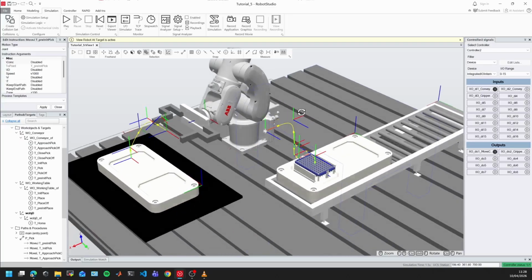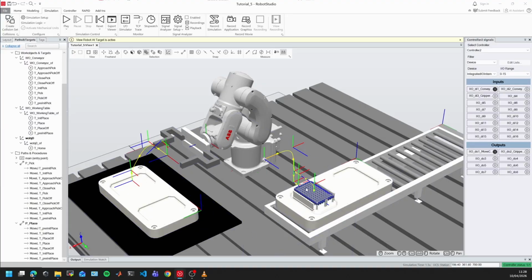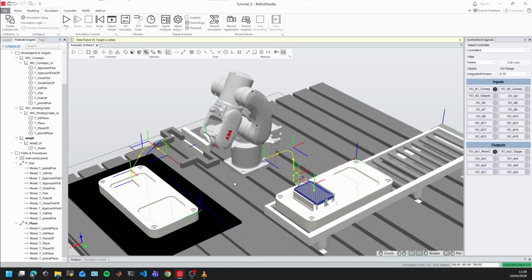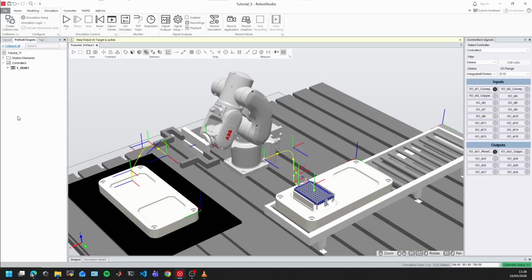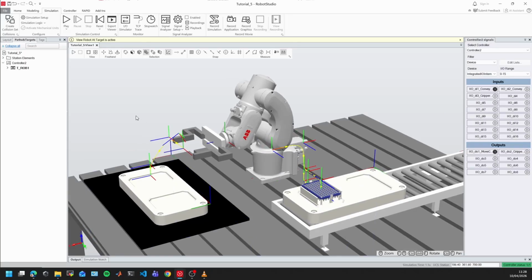To do the pick and place, one of the things that we're going to be using is another event. So what is the event? Whenever the gripper collides with this base, in this case with this PCR plate or fixture, we can capture that event, verify that event, and take decisions based on it. Actually, collisions as events are widely used in ABB RobotStudio.